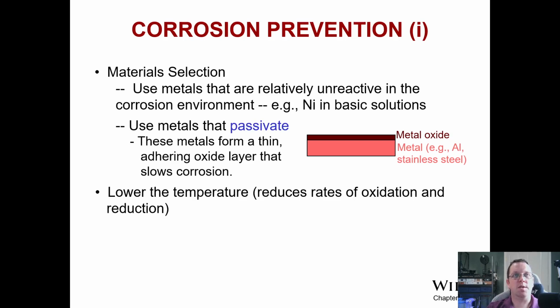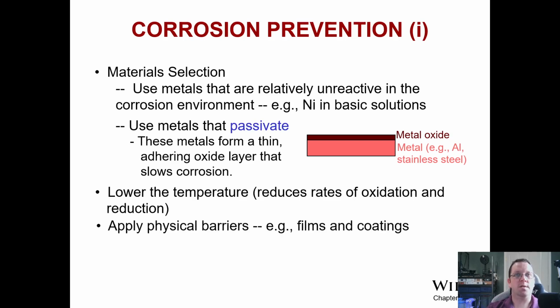And so that's a strategy, is instead of trying to fight the corrosion, let's set up the corrosion such that it now corrodes much more slowly over the course of time, and now it has a much more uniform appearance, instead of allowing it to rust and have discolored different colors and all sorts of things. So having some of the yellow rust and some of the burgundy rust, so they're uniformly rusting the surface so that it has a specific look, instead of allowing it to happen naturally where there's going to be some variance.